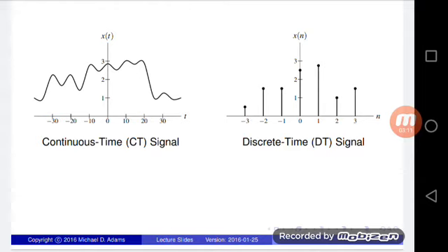Discrete means splitting the analog signal into equal intervals, and then it is converted to a quantized signal. That means assigning individual levels, and finally it is converted into a high state and a low state. High state means positive signal 1 and low state means negative signal 0.